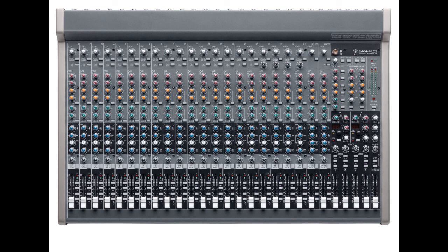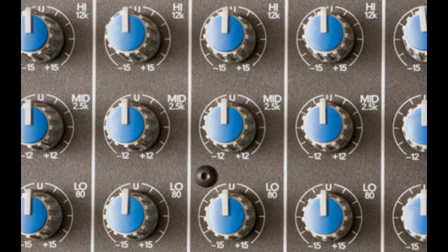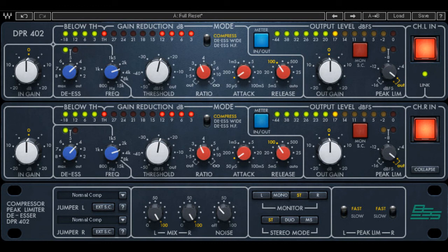Some of the things that we can discuss about these two is that all mixers will typically contain equalizers to shape the frequency response of the signal by either boosting or attenuating relatively narrow frequency ranges of that initial input signal. In addition to that equalization, each channel of a digital mixer is normally equipped with a compressor, a gate, and a signal delay. All of these devices allow you to further shape the sound wave itself.